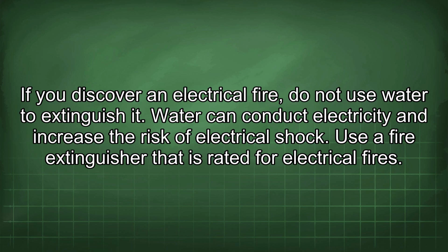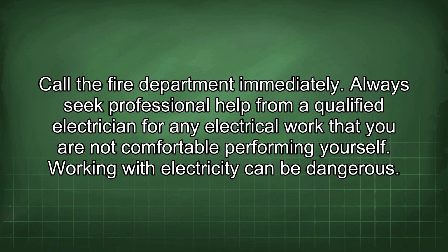If you discover an electrical fire, do not use water to extinguish it. Water can conduct electricity and increase the risk of electrical shock. Use a fire extinguisher that is rated for electrical fires. Call the fire department immediately.